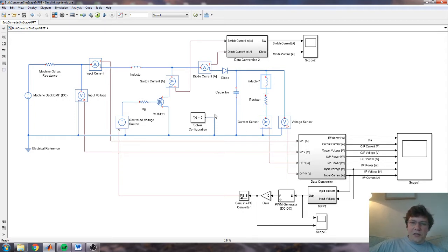If we wanted to be able to have only down conversion, buck would be a reasonable choice, provided you don't want galvanic isolation. If you do, then you might choose a forward converter. If you want the galvanic isolation and you want boost arrangement, you could either modify a boost converter, try a flyback converter, or you can use a forward converter for that as well.